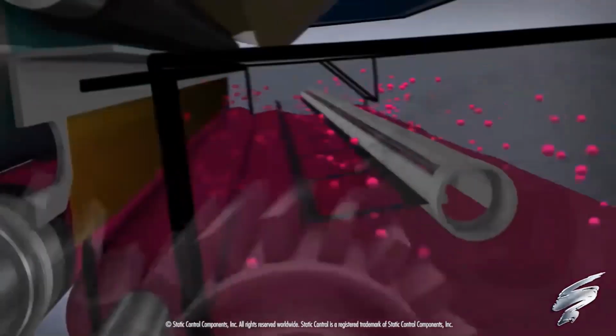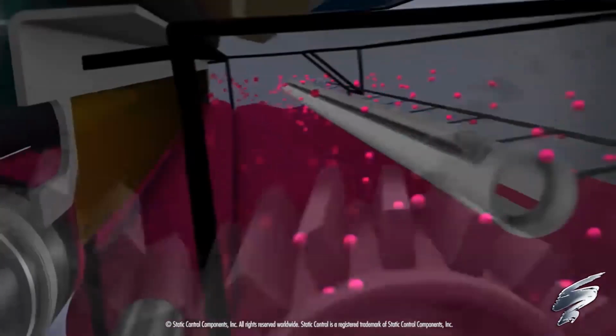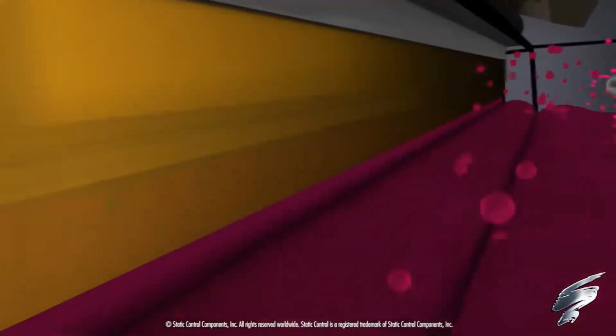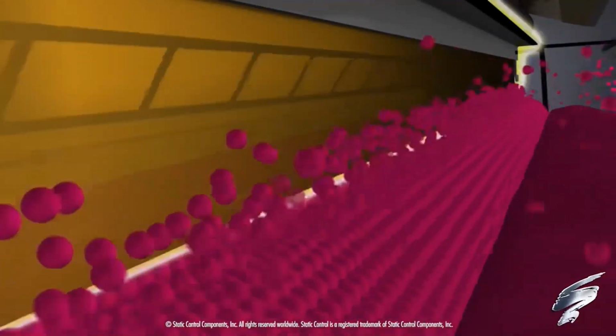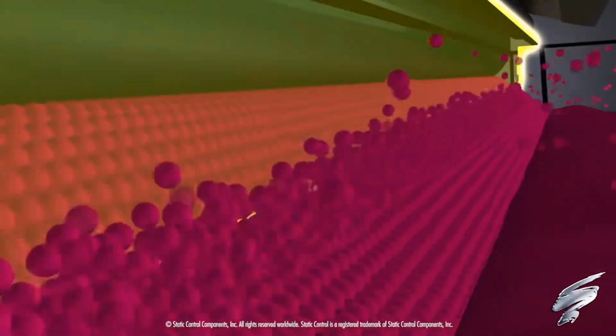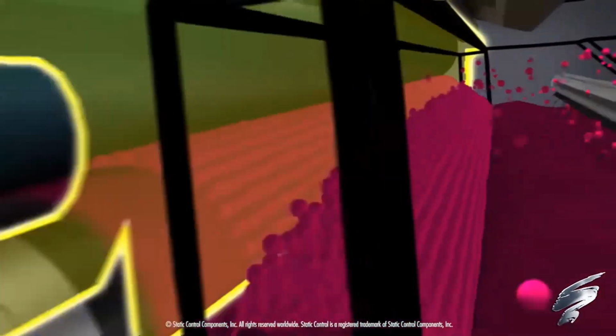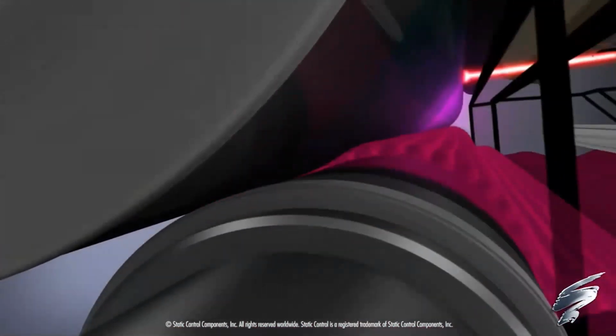Toner is stirred in the hopper. The toner adder roller collects the toner, moving it to the surface of the developer roller. The doctor blade then levels it to the precise height. As toner moves from component to component, it develops a negative charge, which is attracted to the more positively charged image on the OPC drum.